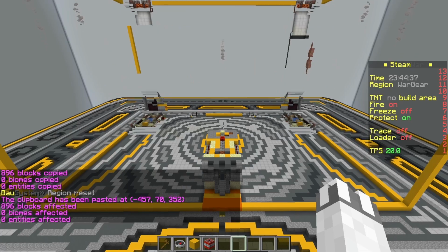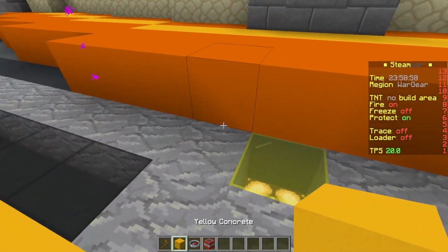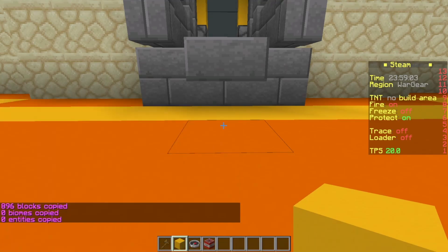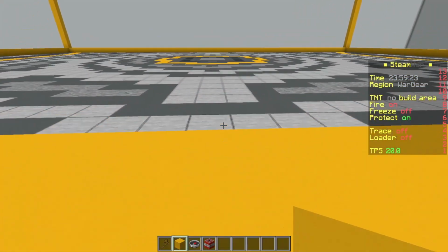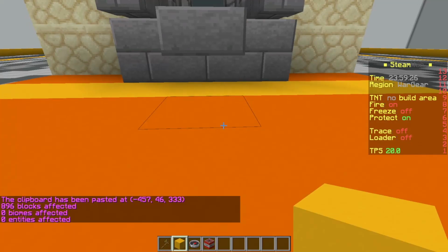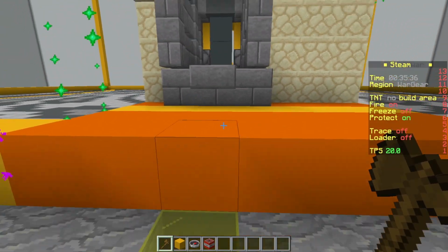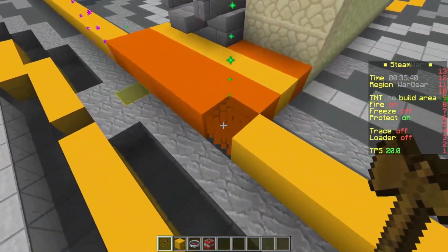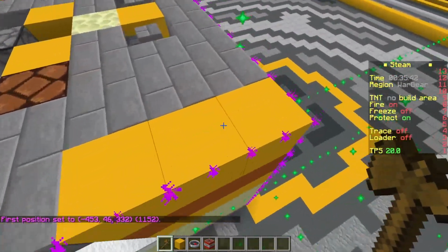or you copy the area from a point you have a reference to, like a specific corner or just the regular copy point, and then go to a different empty plot and paste it from that exact position. When copying instead of cutting, you will very likely still have to cut a little bit because you selected too much, or recopy because you didn't select everything.